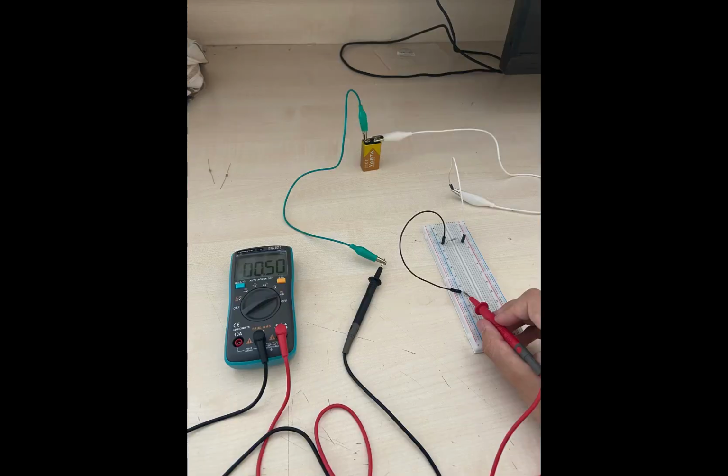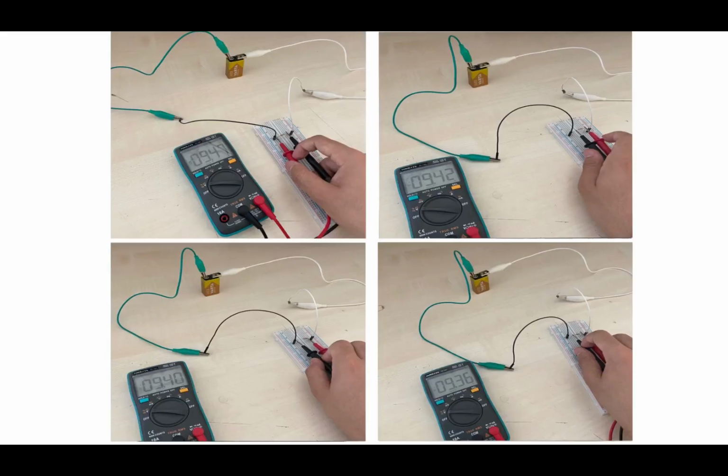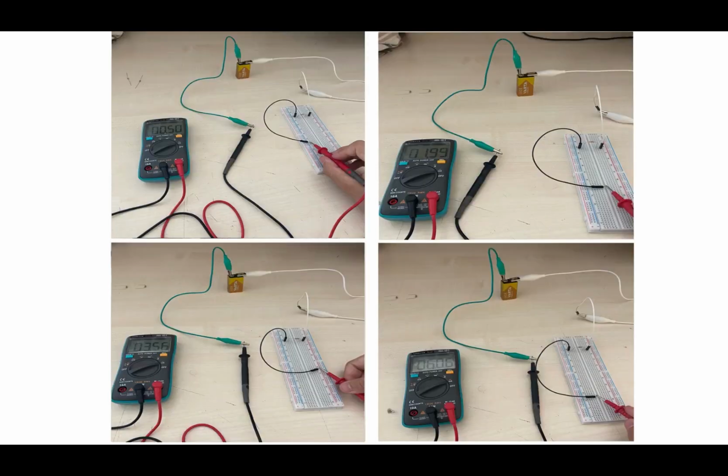I firstly measured the potential difference on the circuit with this design and recorded the results. Then I changed the circuit a little bit to measure the current, which means I connected my multimeter in series to the circuit and measured the current and recorded these results too. Then I repeated the steps for 7 different resistors, and some of the results for voltages can be seen in this image. The current results respectively to the voltages in the previous image were like this.